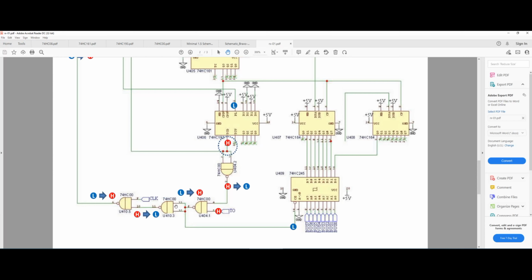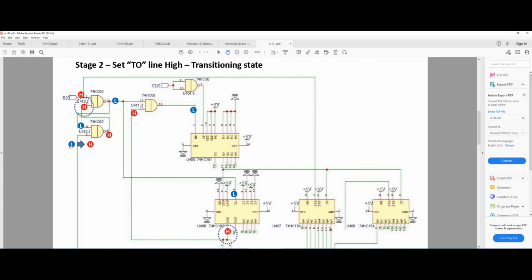We also will be setting the output of that NAND gate to high. And on the rising edge of the clock this time, we're going to have a high, which basically leads to a low signal on the last NAND gate here at the bottom. So that signal was previously high, now it's low. So if this becomes low, then obviously the circuit is going to change, because this time we had a high and a low combined, and therefore we're going to have a high signal output here.